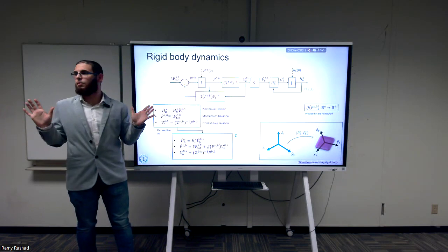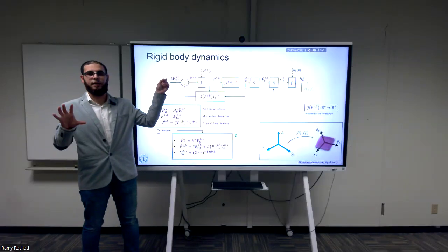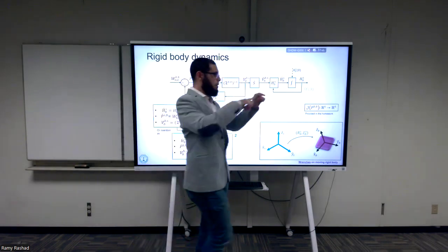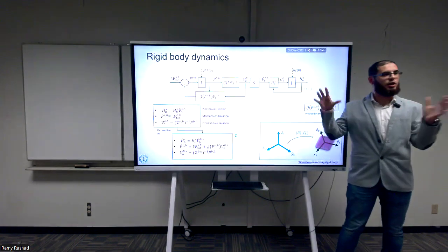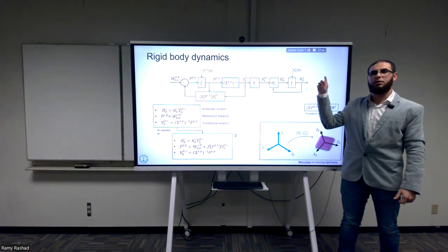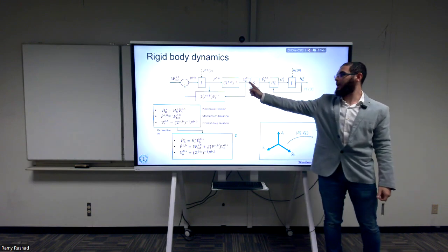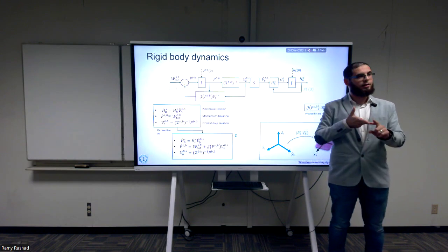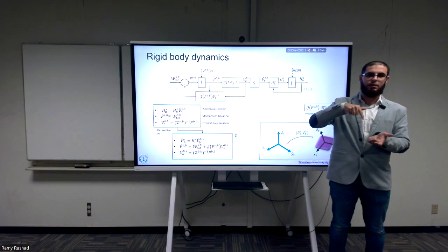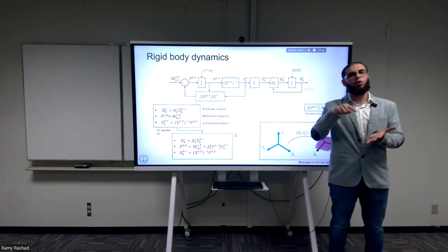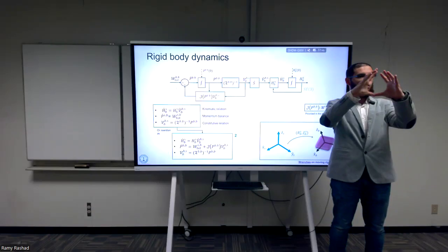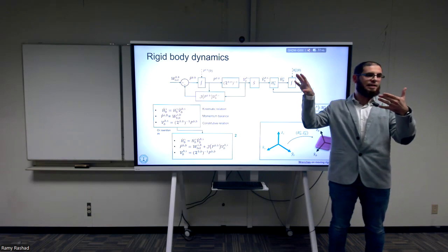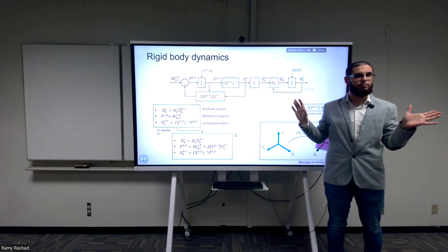And that's it. This is rigid body dynamics. So given the combined forces and torques together, which again make up the wrench, I go through this whole differential equation. Of course, it's a nonlinear differential equation. It's a nasty one, but in the end, I reach the pose and I reach the output. As an output, also I have the twist. Okay? So I have pose or position and orientation, and I have the twist, which includes the angular velocity and the linear velocity, and that's it. So this is our building block, which has forces and torques as an input, and pose and twist as an output. Okay? And we're done with the dynamic model.